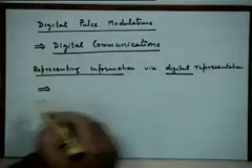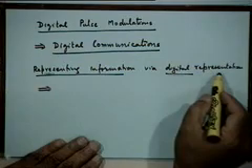The simplest example of discrete amplitudes is to have only two amplitudes, ones and zeros, but a more general representation would have several amplitudes, maybe 4, maybe 8, maybe 16, right. You can have a fixed number of amplitudes. You work only with a fixed number of amplitudes. Now, how do you represent a signal which has continuously varying amplitude with another signal which has only a discrete set of amplitudes to work with, right? And when you do that, you are able to convert that analog information into digital information, right?